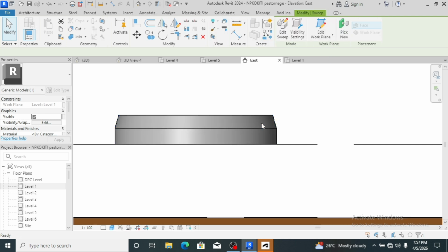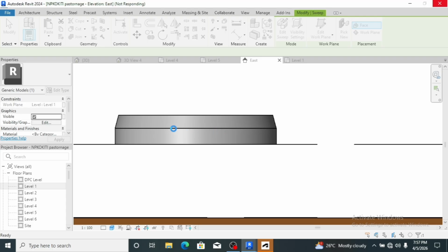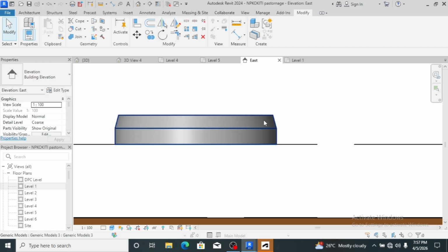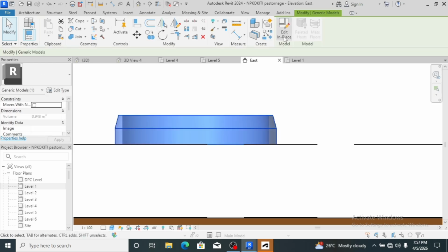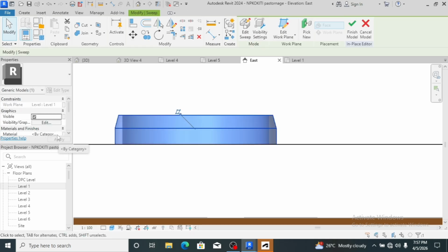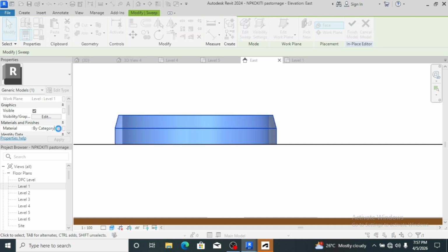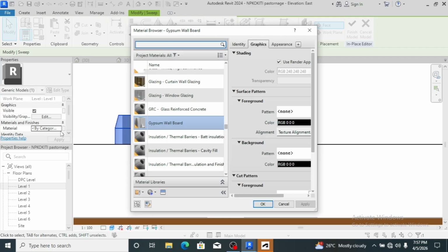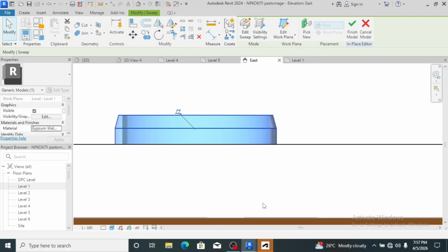Meanwhile, let's save. Then we need to set its property. Let's set its property. Edit. Highlight. Category. At the material edit at my right left wing, category here, there's a three dot there, highlight it, come to category, gypsum board, confirm, yes, highlight.